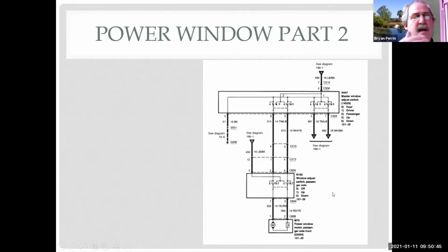And to give you an idea, I was in the shop and I had my boss and one of the other technicians working on a power window system, and they'd been on it all day waiting on some parts back and forth, and it wasn't working. And they came to me and said, Brian, can you take a look at this? We've put a new switch in twice. We've done this. We got everything torn apart. It's not making sense. I look at the schematic, figure out what it is, and figure out that the brand new switches they were getting from Ford were made wrong. And I actually had to cut a connection inside the switch, and then everything worked right.